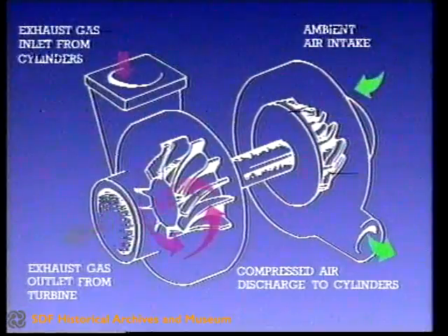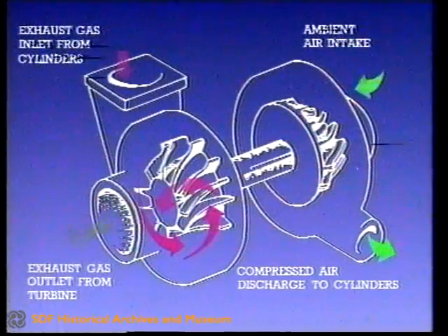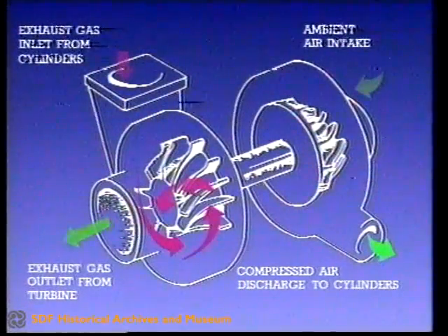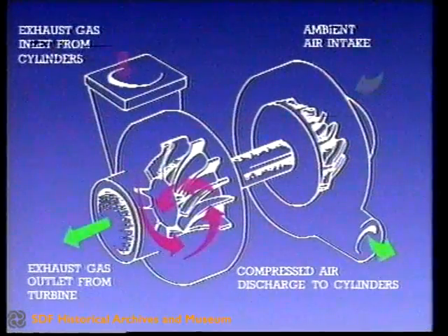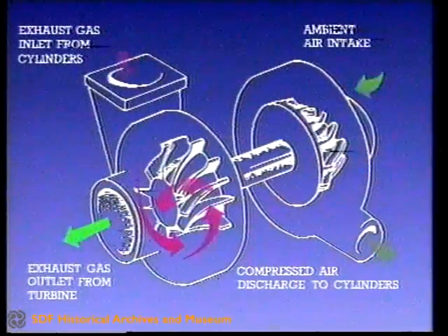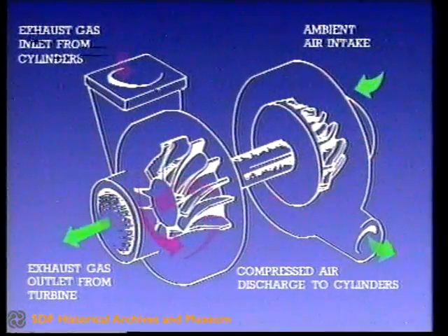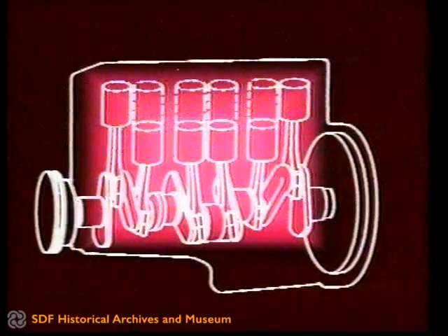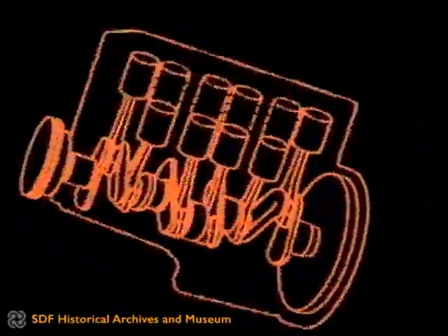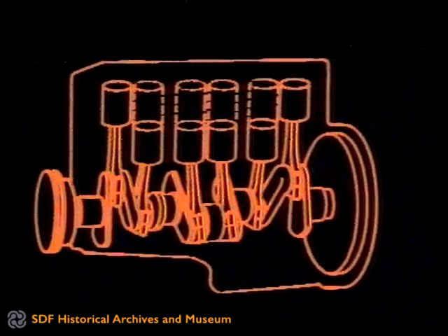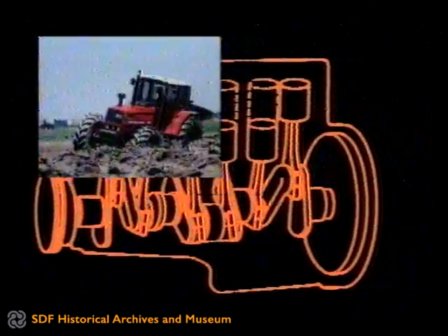Turbocharging is the sole method of increasing power efficiently whilst maintaining a compact size and weight and without reducing engine reliability. The other main methods, which do not, however, allow for achieving these results, are by increasing cylinder capacity, by increasing both weight and dimensions and possibly even the number of cylinders, or by increasing the maximum speed of rotation. This increases the mechanical stresses on the engine and lowers its volumetric or induction efficiency.